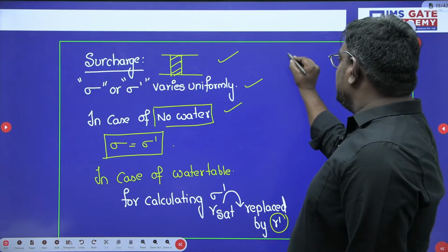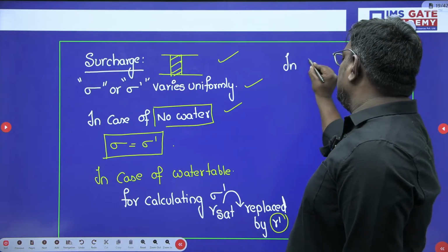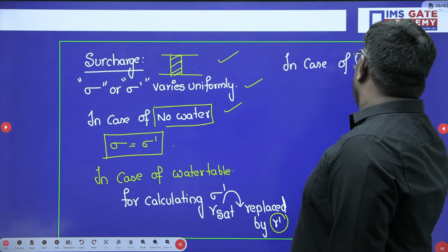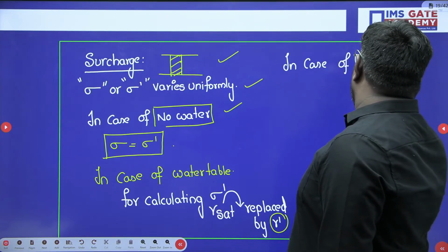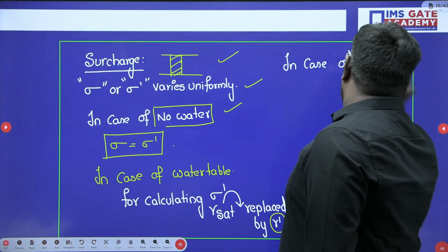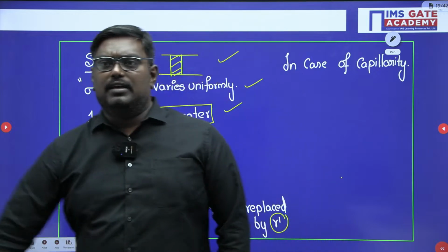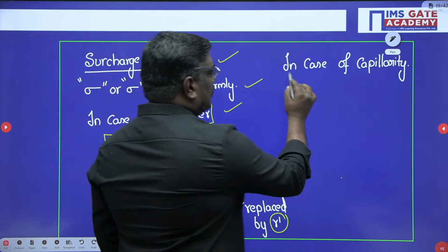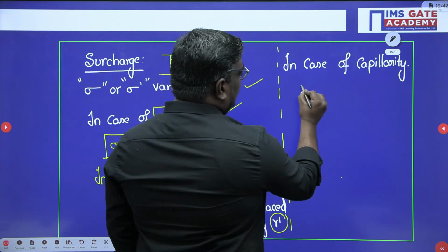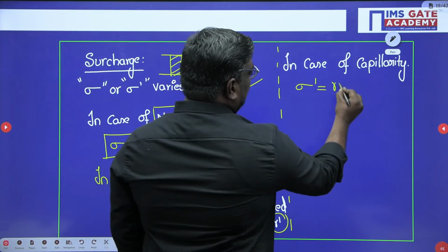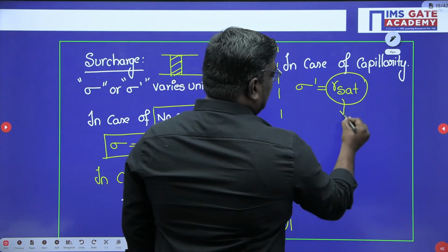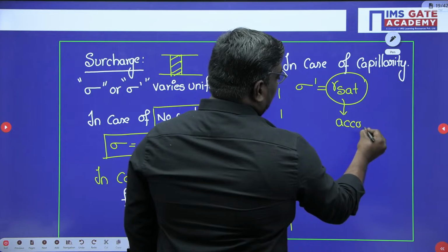Now see, students, in case of capillarity, how do you calculate effective stress, sir? In case of capillarity, effective stress is calculated by taking gamma sat into account.